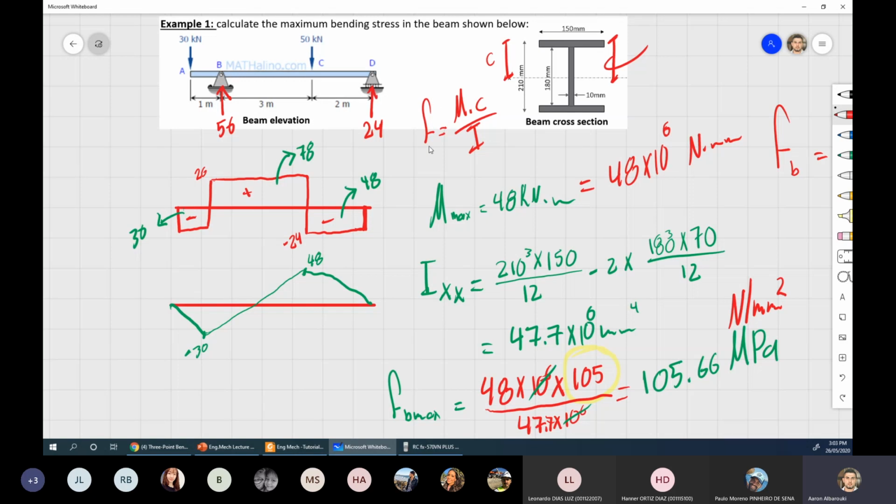Look at this. By knowing the forces, we learned how to calculate the maximum shear and maximum moment. By understanding the strength of material and the property of that cross-section, which is the moment of inertia, as an engineer, you have the knowledge to quantify that. To resist these forces, for this cross-section, and for a different cross-section we can come up with different numbers because I value will be different.